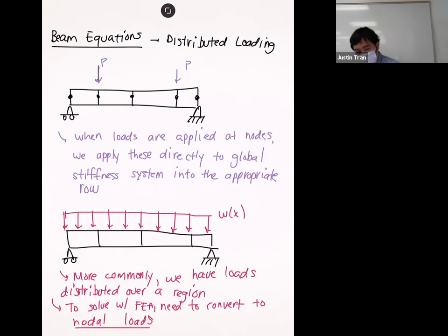Okay. And so that's what we're going to spend most of the time doing today: learning how we take a distributed loading like this, where we have a load spread out over a region of space, and convert that to loads that are applied at the nodes.